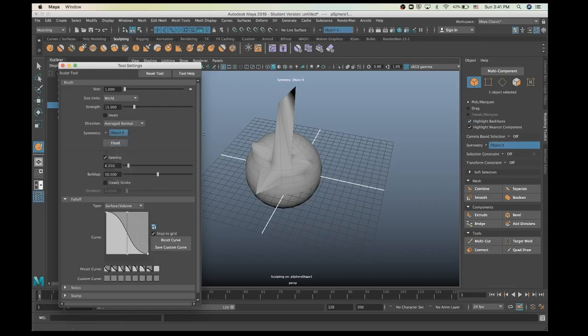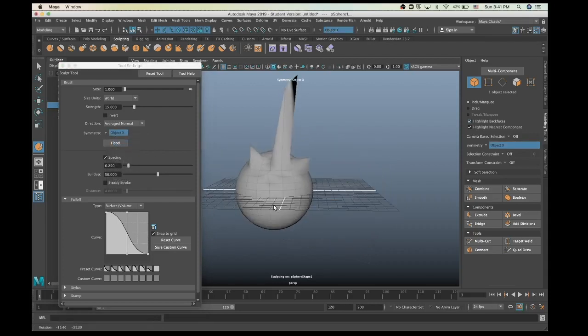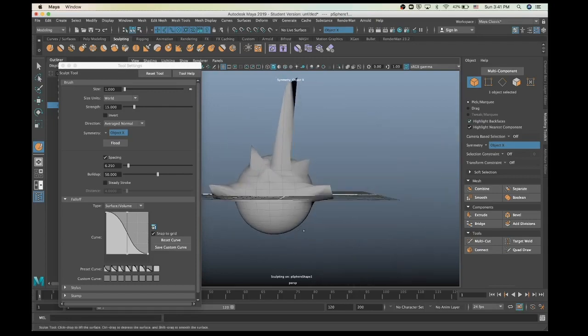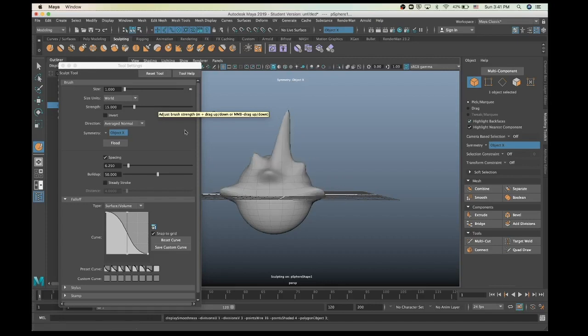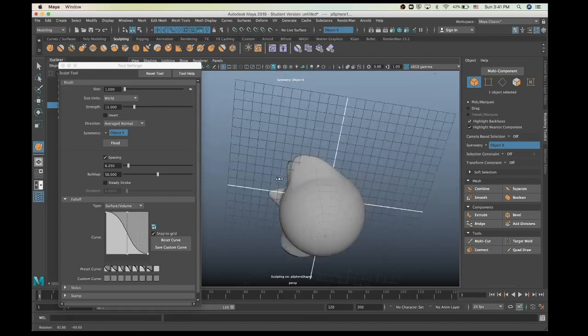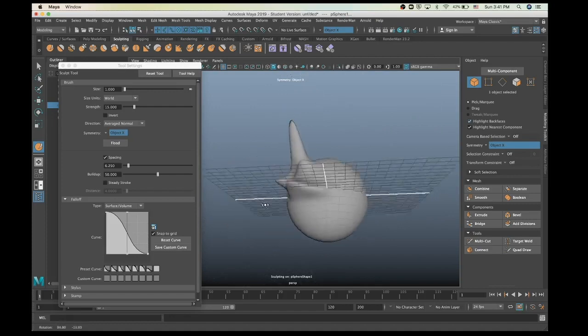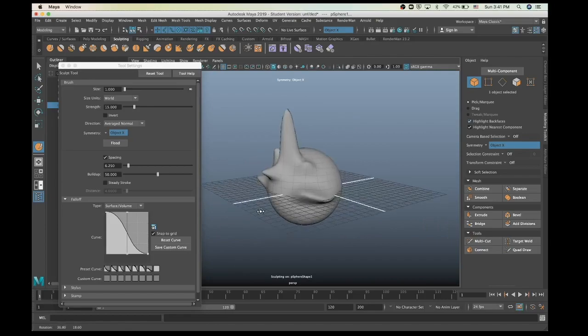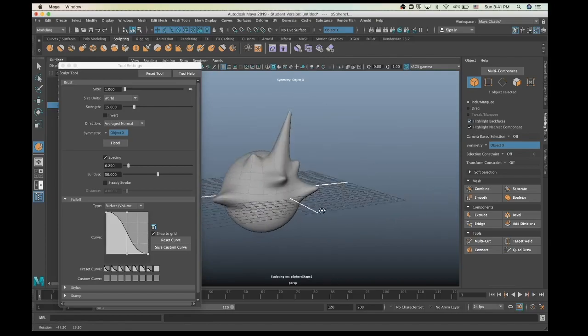For example, I choose object X, and as you can see, my brush is duplicated in two, and if I work with it, you can see it is sculpted on both sides. And if I, for example, press 3, now you can see the changes that I add to my mesh. It's like a smoother, making it smooth.